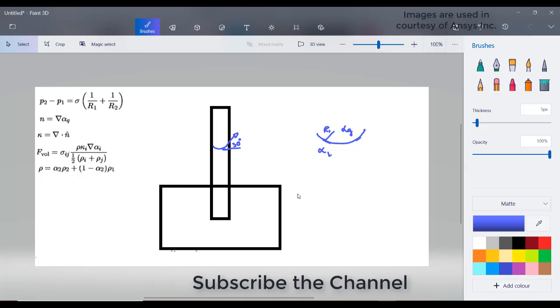Now, this is the term that defines the forces generated due to the surface tension inside Ansys Fluent, or inside any commercial tool we use. So this is P2 minus P1 equals surface tension times (1/R1 plus 1/R2). R1 and R2 are the two radius vectors in perpendicular directions. If this is R1, this would be R2 along the curvature.